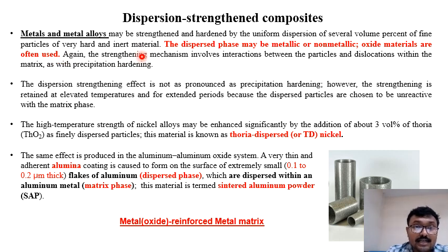Again, the strengthening mechanism involves interaction between the particles and dislocations within the matrix, as with precipitation hardening. The dispersion strengthening effect is not as pronounced as precipitation hardening.